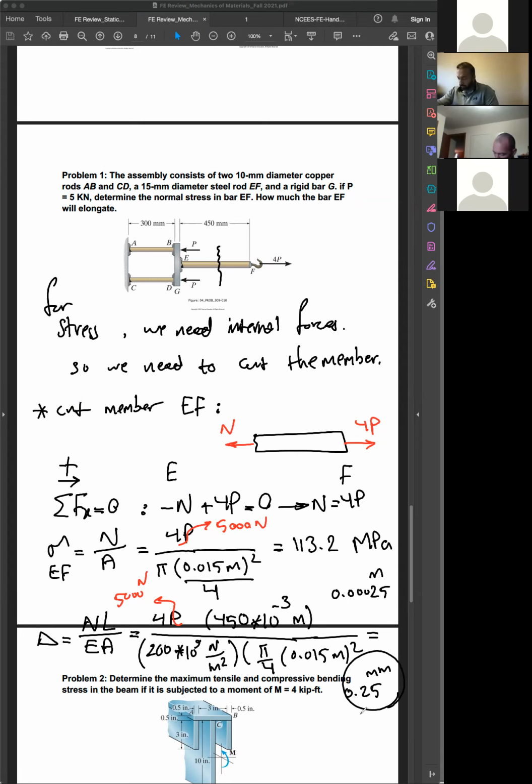Questions? So if the problem was asking you what are the internal forces at A, B, and CD, the same idea applies. You need to cut, select the left and right, use equilibrium, find the internal force, and just continue the problem. The essence would be the same.